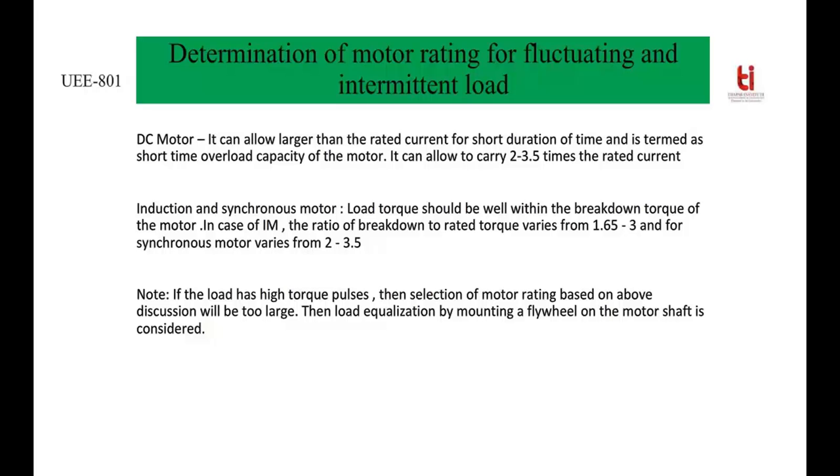In that case, we have to use load equalization by mounting a flywheel on the shaft of the machine to generate extra torque, or to support the driving torque of the machine. The flywheel will supply the stored energy to support the developed torque to cope with the load torque.